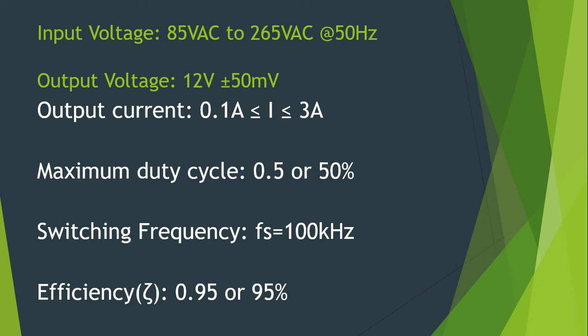Sorry. So how about our input voltage? Our input voltage, we want it to be from 85 volts to 265 volts. There are some countries where the voltage is less than, I think, 100 volts or so, if I'm not mistaken. And sometimes your mains may not be high enough to power up at 250 volts. So you have to set it to be less, 85 volts. So once the voltage reaches this 85 volts, it should pick up and start working.